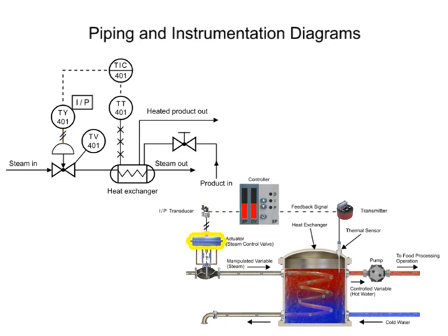The pneumatic-controlled diaphragm actuator that opens and closes the globe valve regulates steam in the process. The actuator is represented by the half circle in the P&ID. The arrow pointing downwards from the actuator indicates a fail-closed valve type.